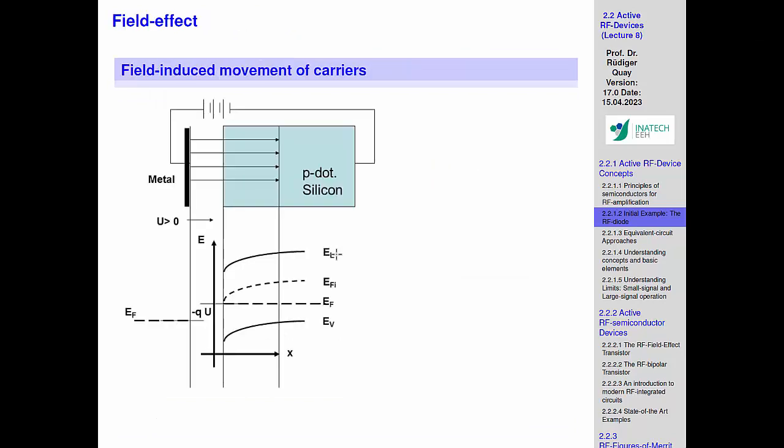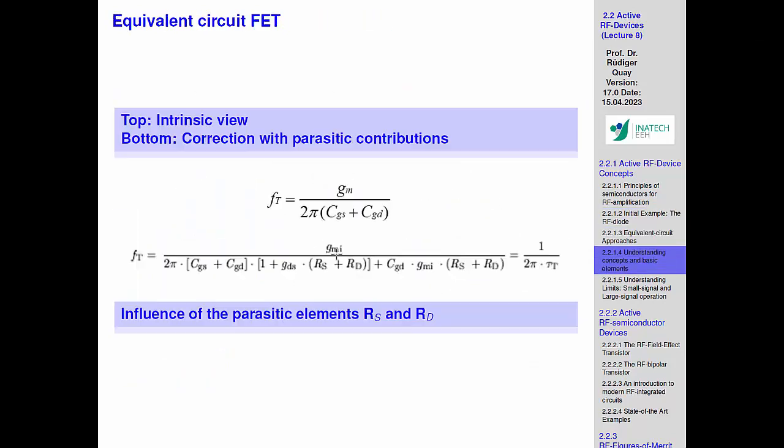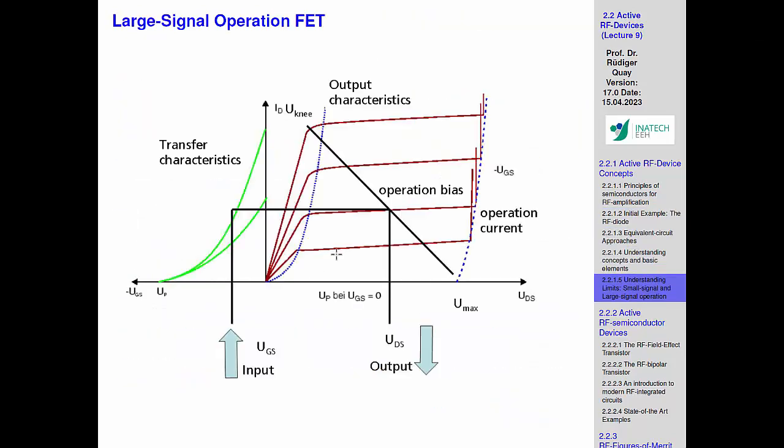And you see there's also a lower side for the current or the voltage to swing to. That is essentially defined in this linear region, where we have inversion, but it's more resistance which we control here. RF-wise, this is also interesting. It's not for amplification, but we can control a voltage, so you have a controllable resistor with little or no amplification. That can also be a nice function, but it's a different one.